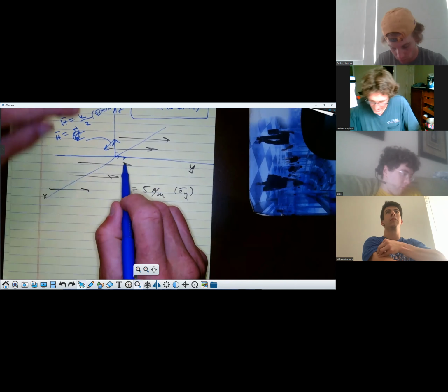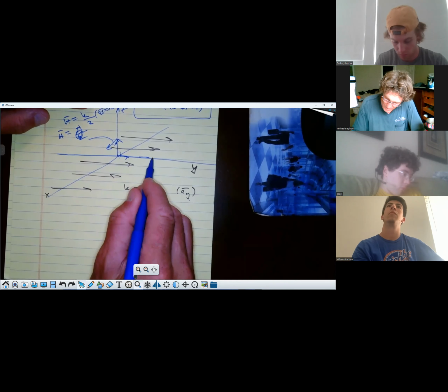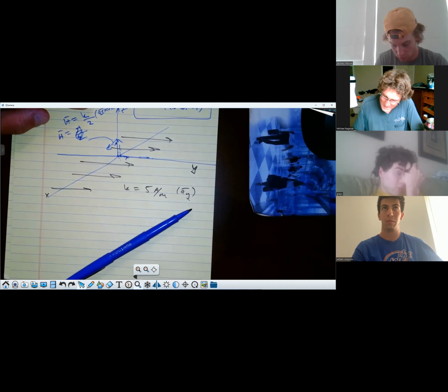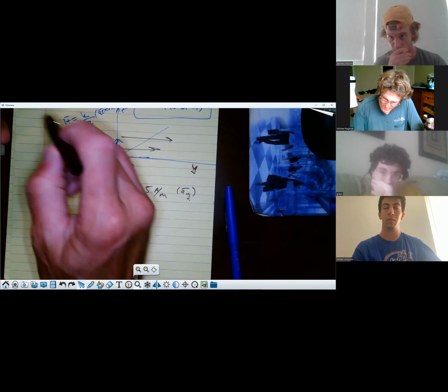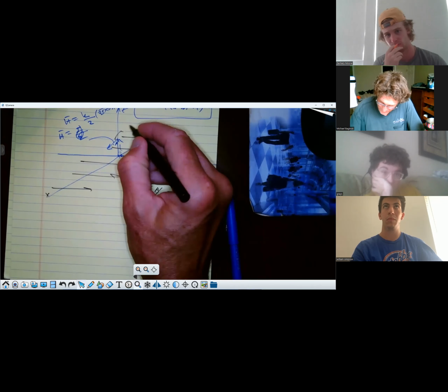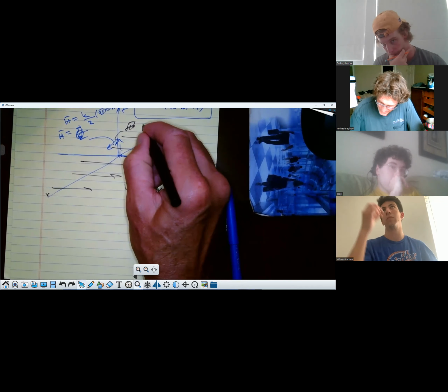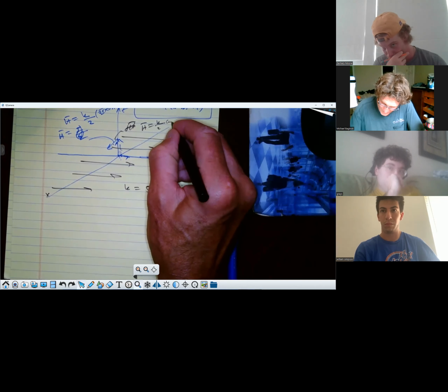So if you look at this above it, a_I is in the Y direction, a_y, crossed into a_N, which is a_z. So Y cross Z is a_x. The actual H field there above it would be equal to K, 5 amps, over 2 a_x.